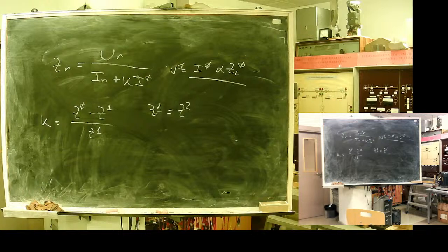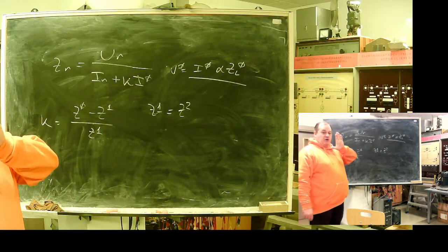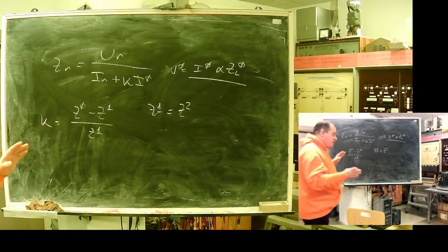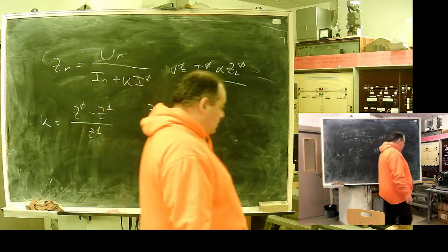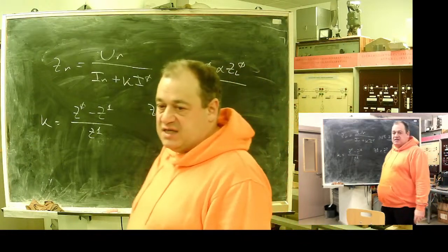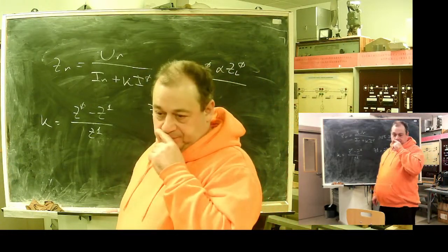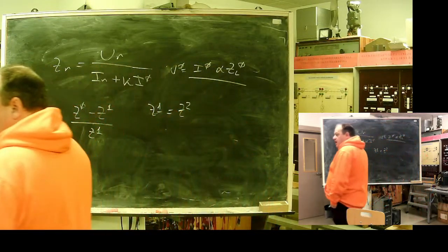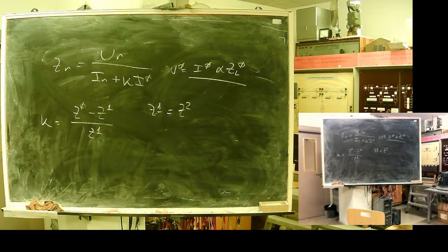If fault resistance is low, again, it's okay, because on a metallic fault we can separate the zero sequence schematic without any problem to the left and right side of the fault, and this will be true. But if our earth fault is with transient resistance, and we have a path for zero sequence on the opposite side, error is unavoidable.